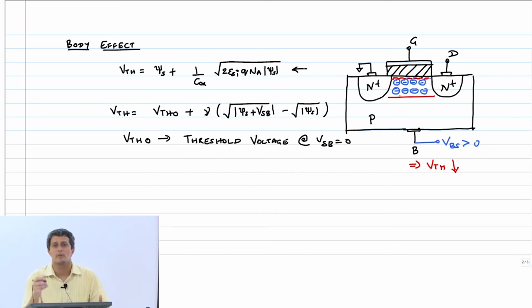So you make measurements on the transistor for certain lengths, certain widths and all that, and then you can guarantee that this is the best fit for these particular parameters. But if you change it arbitrarily and apply a very large width or a very small width, then there is no guarantee that the model will work. This is the flip side of an empirical model. It simplifies the equation but does not guarantee scalability into all regimes of operation.